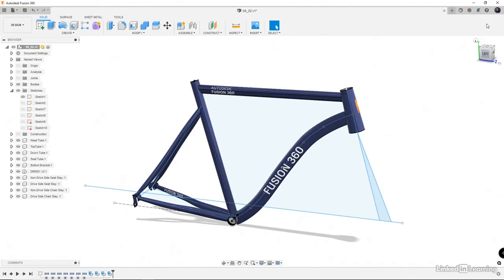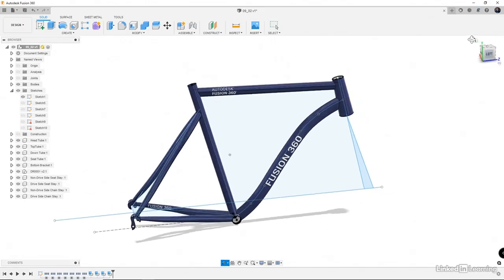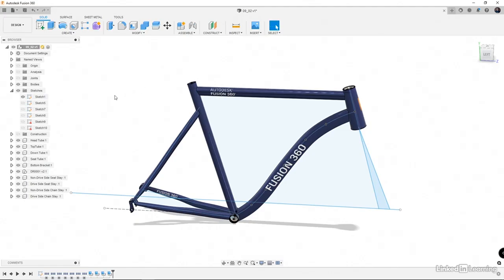So this is a way that you can use a 3D geometry and it references all of the bodies to the geometry. And if we update that geometry, it'll drive everything. Now, it doesn't always work seamlessly, but it works really well for an assembly like this. We might just have to go in and fix one or two little minor things if we update geometry that's a little funny. So let's kind of go in and see what's going on. So it's this number one sketch, and this is what drives the entire thing. And you'll see there's some other sketches, and these are all driving components within it.